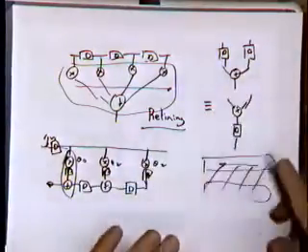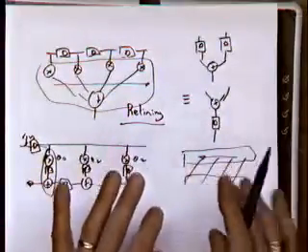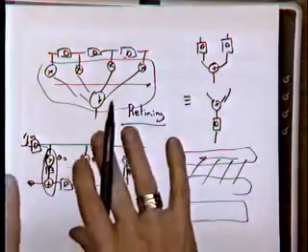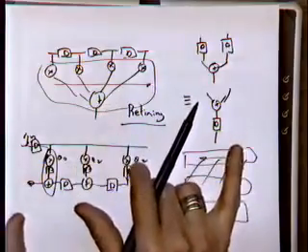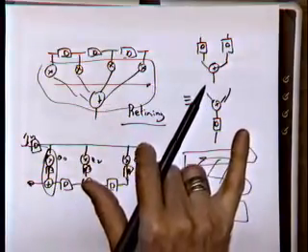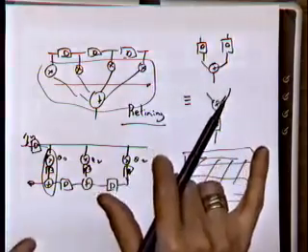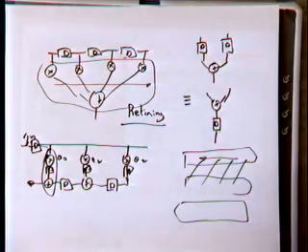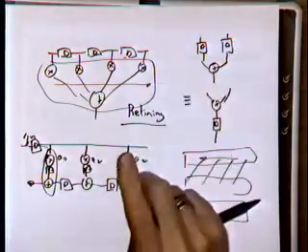In this way, you can actually play around with where your critical path is, and then in the end, I can use a carry select adder or carry look ahead adder. Not the traditional carry look ahead. A lot of you figured out that this combination of select and ripple works quite nicely. For instance, you take an adder, you divide it into 2 blocks of 4 bits, or 4 blocks of 2 bits. You do carry look ahead on each of those, and then you ripple the carry forward. For a small adder, it works really nicely.